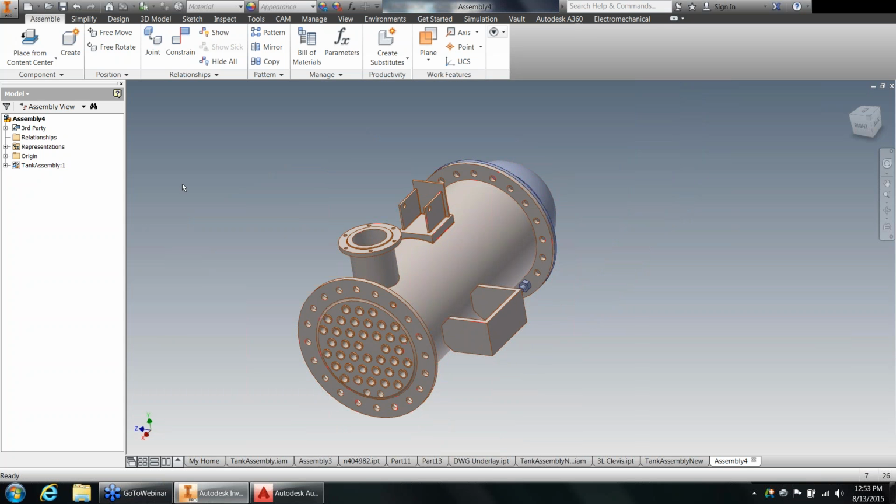But again, as far as adding constraints, adding objects inside of here, if I were to bring a gasket component in here and constrain it, if that were to move positions, rotate around this part, move up and down, change diameter, those sort of changes wouldn't necessarily change the face IDs, so all of my constraints and joints would trickle across. Now, if they went from a round one to an octagonal one, then the whole thing's going to be a wash, right? Because all those faces are going to change. So it's really just dependent, just like in Inventor, on what the changes were made.